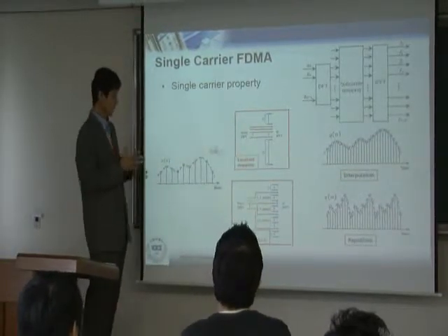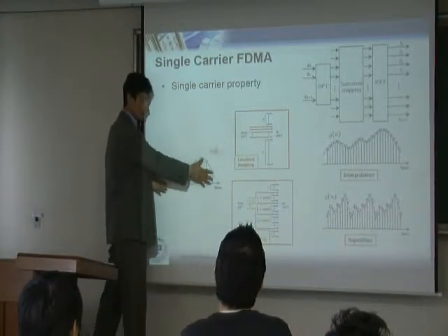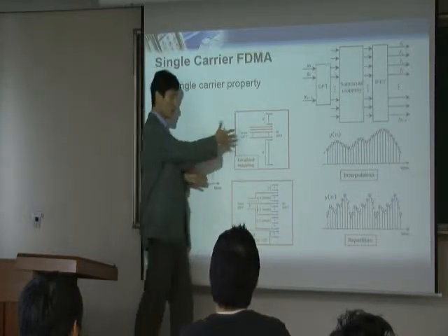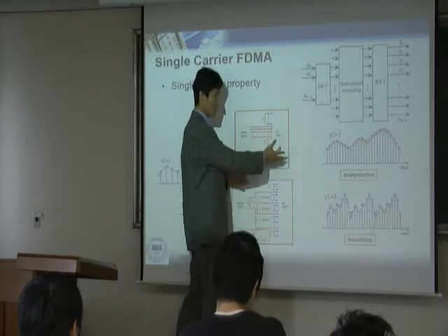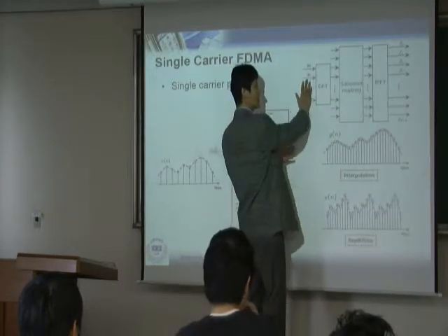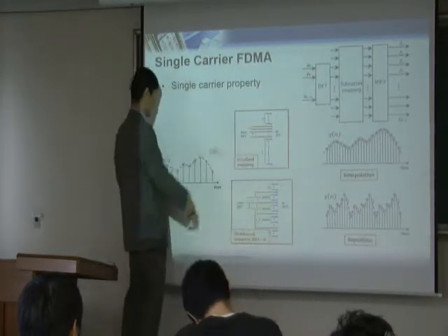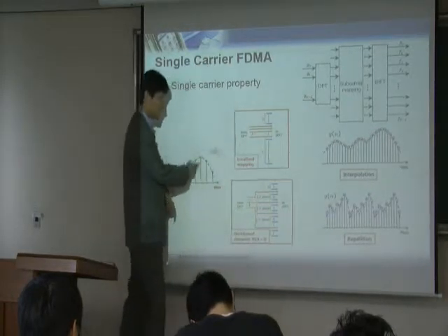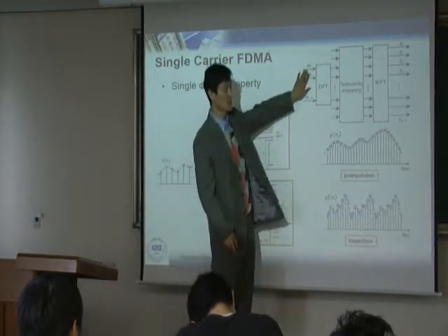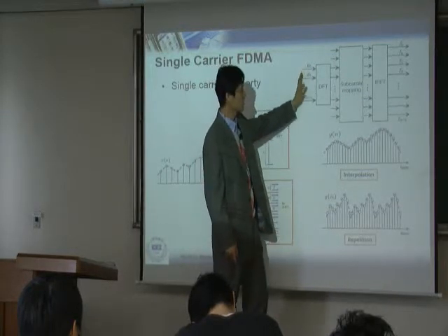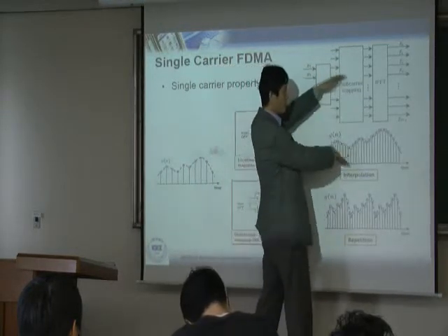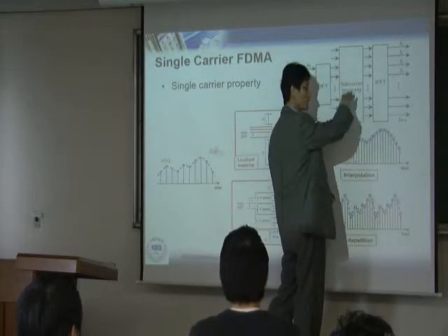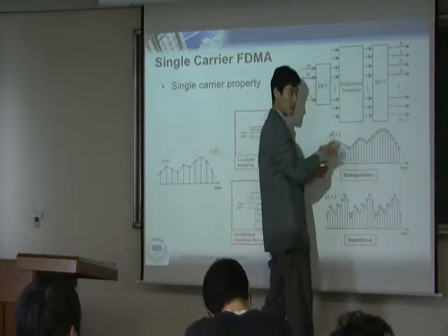What happened is that this was the original signal, right? And you do this whole thing. And in this case, this is the original thing here. This is time domain, so you see this signal right here in time domain. What you do is go to frequency domain, do a zero padding, and come back to time domain. You do the zero padding in frequency domain.